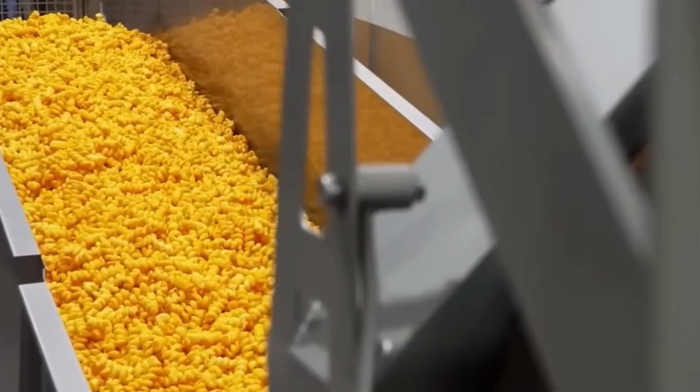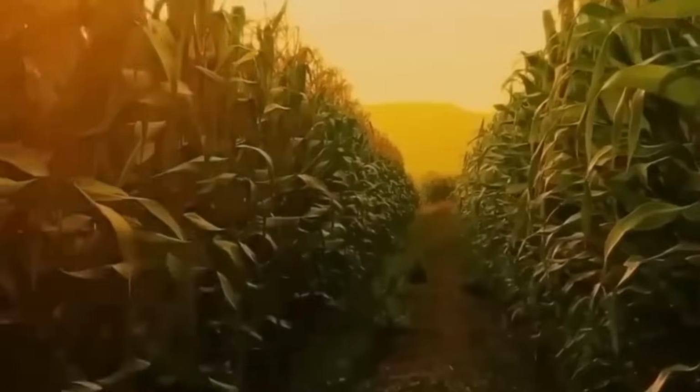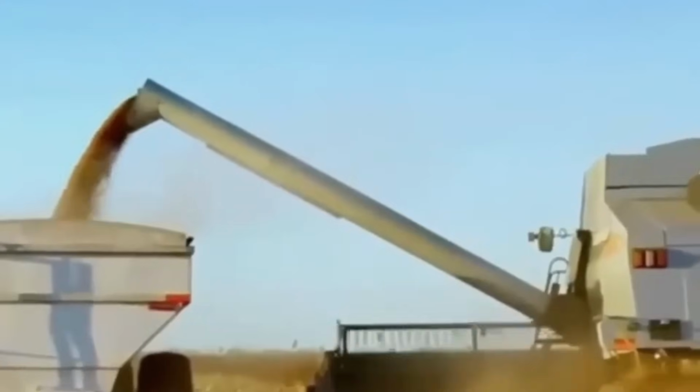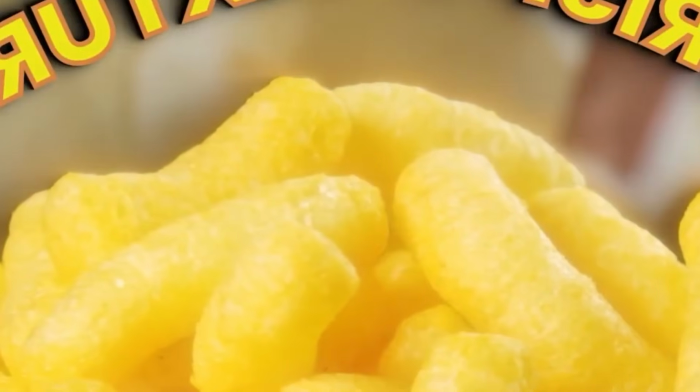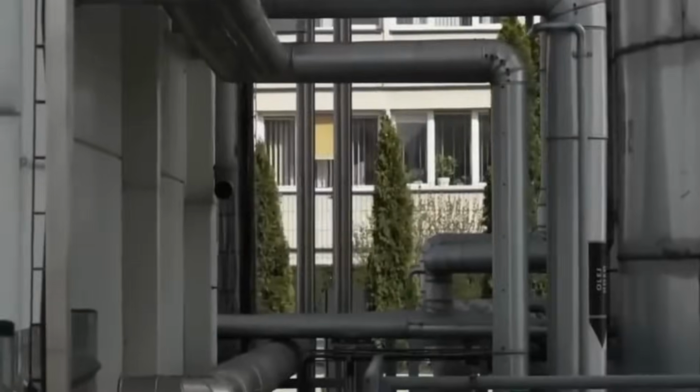After frying, the product is lifted out of the oil and passes through a cascade of air knives or centrifugal de-oiling drums to remove excess surface oil. The fried product is then conveyed through a multi-stage cooling tunnel where ambient or chilled air flows across vibrating trays to reduce product temperature to under 40 degrees Celsius before seasoning. Airflow is adjusted with dampers to maintain a uniform cooling gradient and avoid moisture migration.